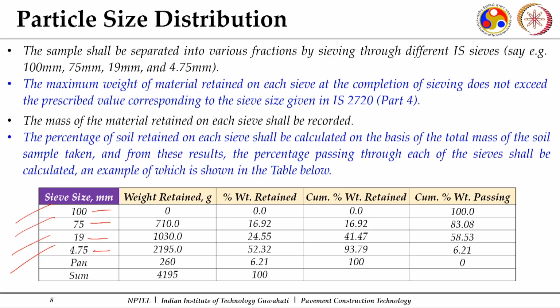So, what I will do is take a standard material, put it on the top sieve, and it will be shaken. Now, you have laboratory sieve shakers also, and sieves of different sizes are also available. You can have 15 centimeter diameter sieves, you can have 30 centimeter diameter sieves. All those different sizes of sieves are available